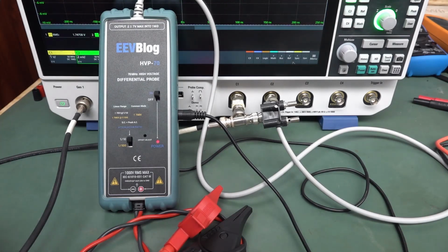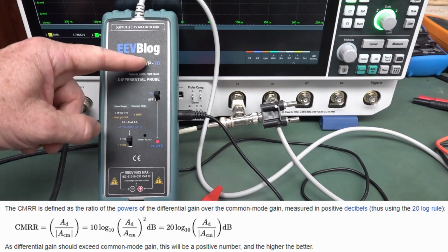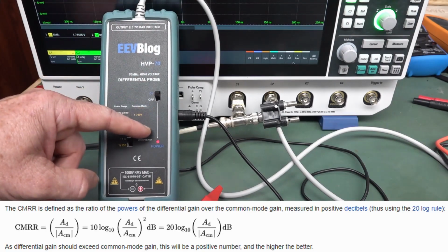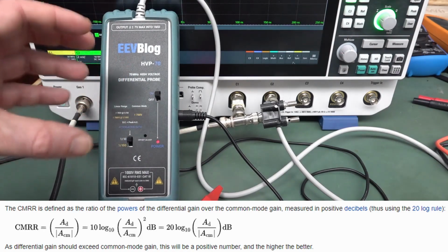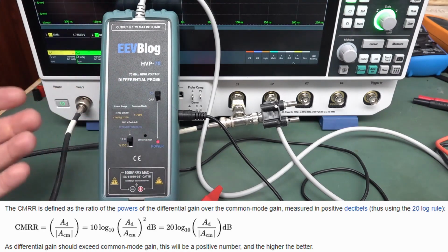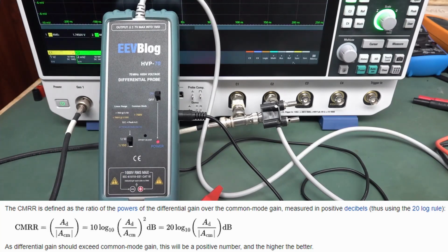And the interesting thing about this is that the common mode rejection ratio is, as I said, the differential gain divided by the common mode gain. And that actually comes out at a positive value. So why is the data sheet negative? Well, there's no standard for this kind of thing.